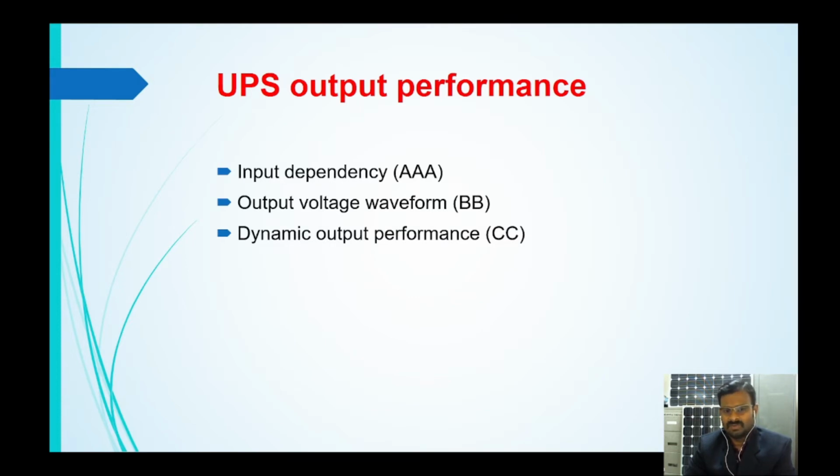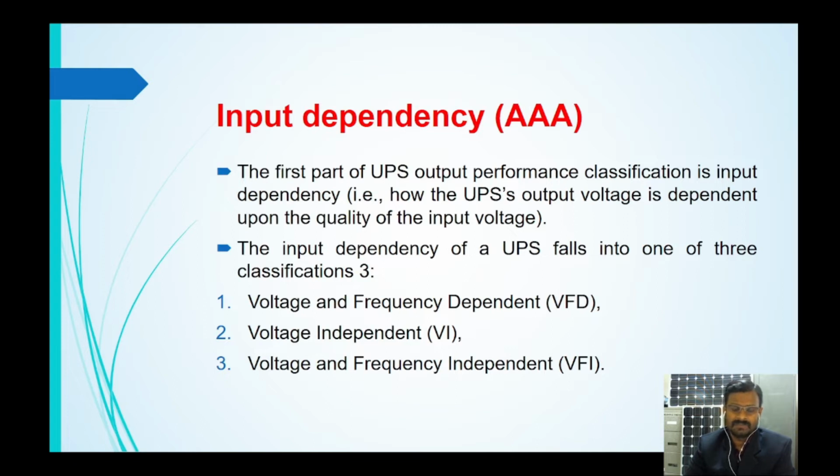First, let us see what input dependency is. Input dependency means whether the output of the UPS depends upon the input voltage magnitude and frequency, or is independent of these parameters.